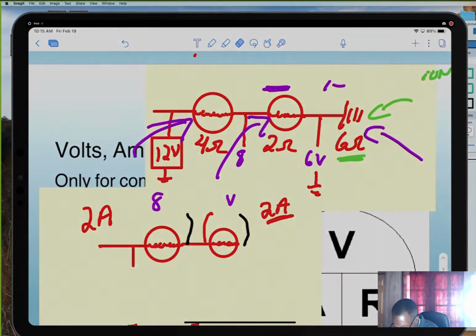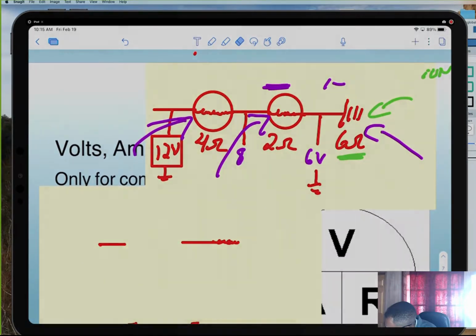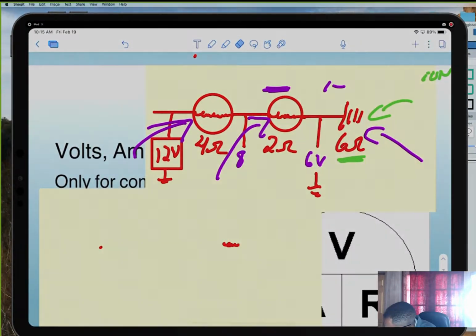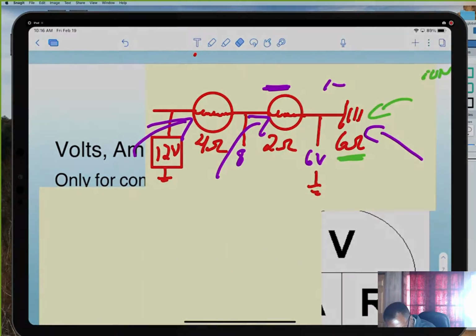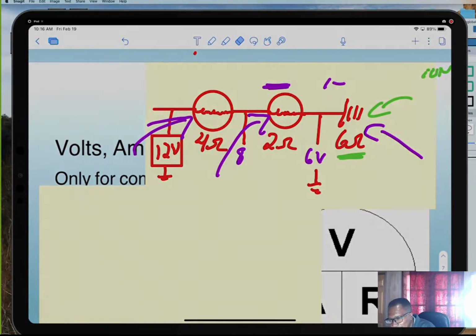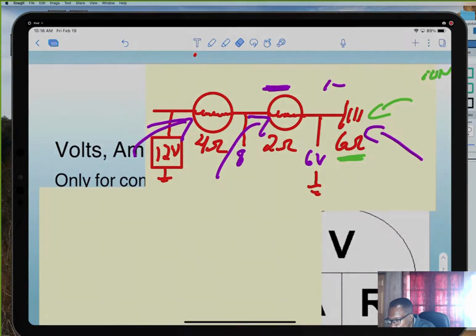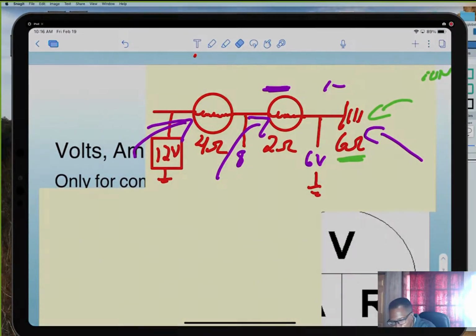Anything that happen with the short? What you mean? Like if you have any short in your car, anything like a wire touch another wire. If a ground wire shorts the ground, really nothing happens unless it's ground control. But if a positive wire touches the ground, it's gonna blow a fuse. That's an open circuit.